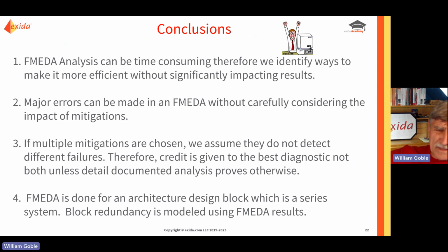The FMEDA is done for an architecture design block, which is internally a series reliability system. Any component fails, block fails. Block redundancy is modeled using the FMEDA results in a Markov model or a fault tree.